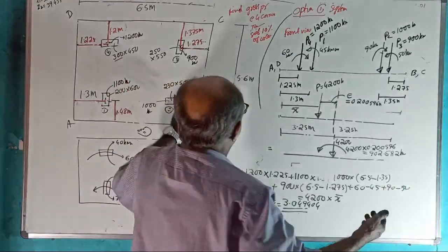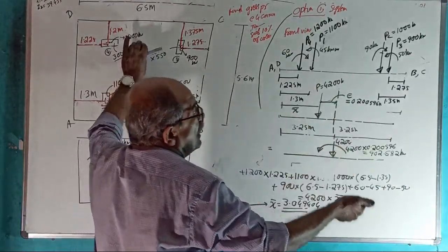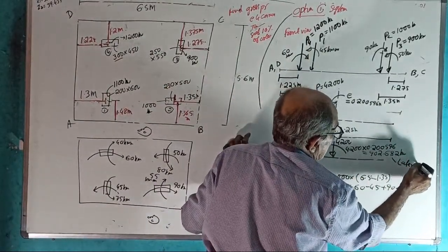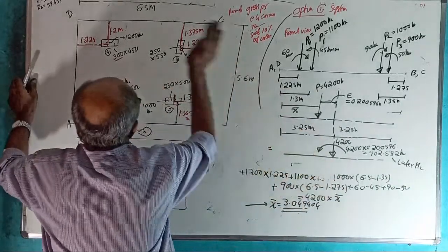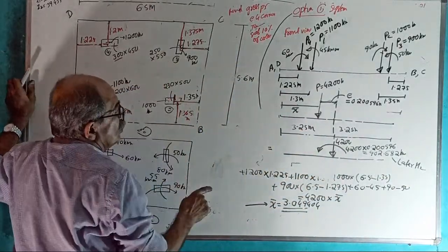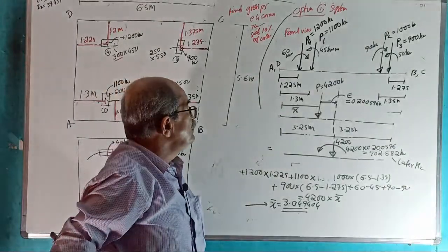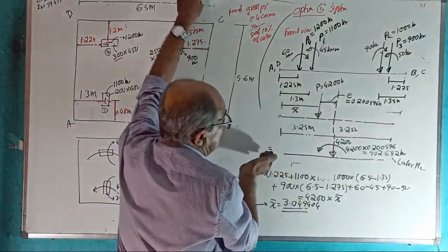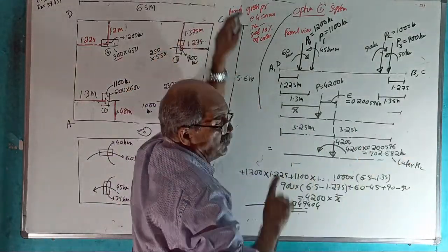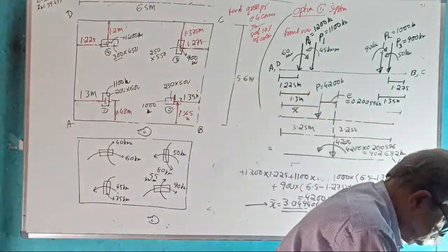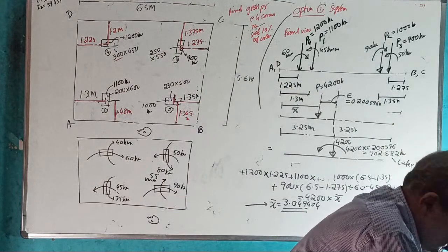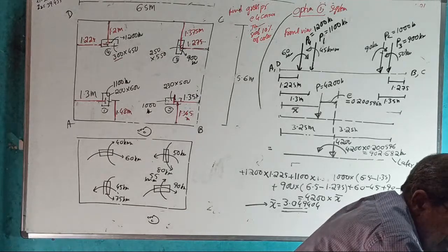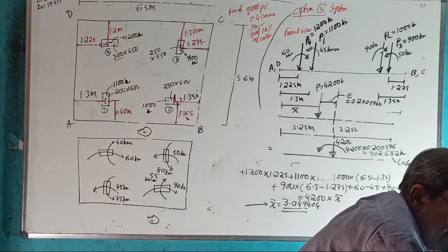Therefore, later remember your P is 4200, and I told you one lengthwise moment. If you remember, this moment was M2. I told you this moment is M2, this is M1. So later your M2 becomes 902.682 anti-clockwise. So for the pressure calculation, this side is positive, that side negative. Fully clear? This is the final load and lengthwise couple.